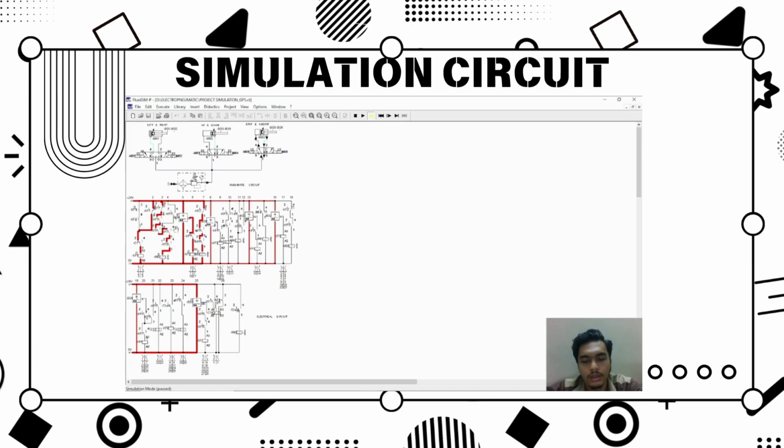and relay contact -KF7 will open and deactivate solenoid coil -MB3 and de-energize coil relay -KF6, -KF2 and timer -T1, and relay contact -KF7 will close and activate a counter -C1 for 7 times, and push button -SF3 as a reset button for the counter C1, and this simulation will continuously cycle for 7 times.